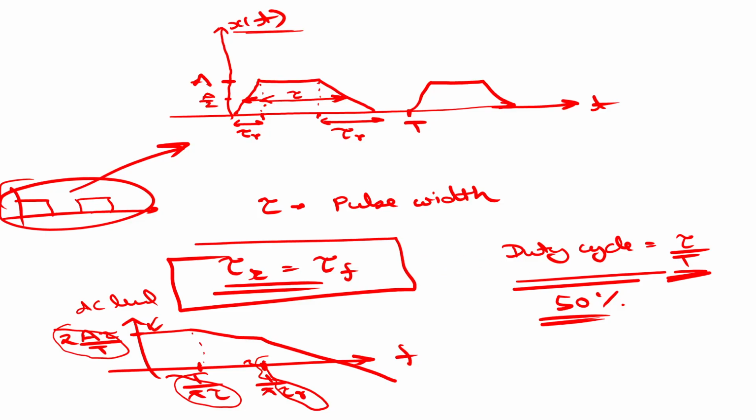So we can clearly see that the duty cycle change, if we make it from 50 to let's say 30%, will not affect the high frequency component of the clock, because this remains the same, right? So any frequency after this will not be affected. Now just a second.